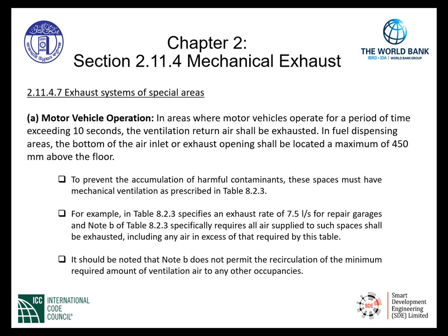It should be noted that Note B does not permit the recirculation of the minimum required amount of ventilation air to any other occupancies.